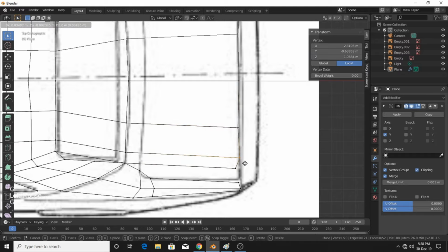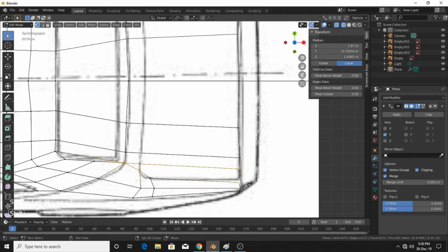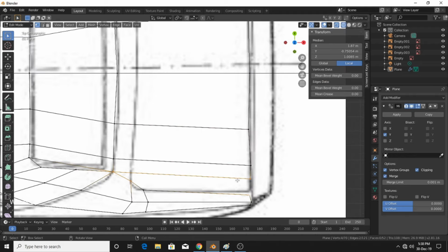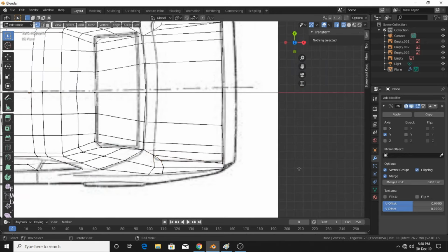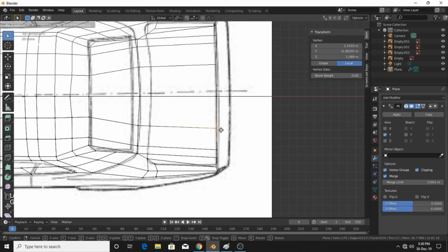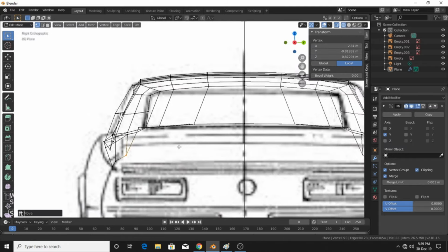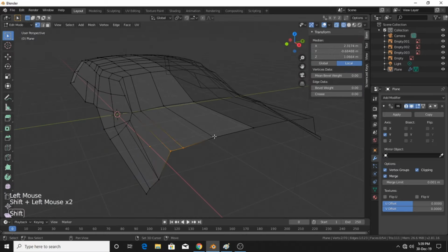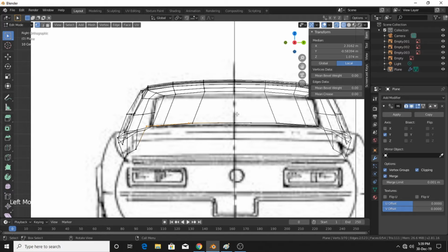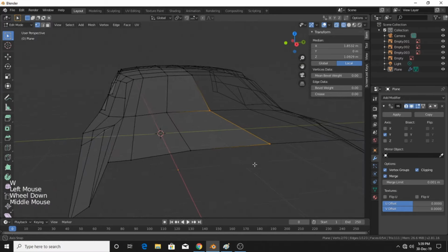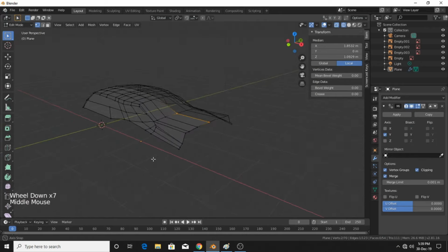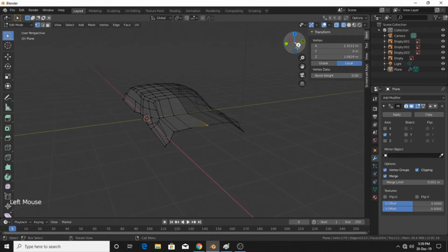Now just select these 3 points and extrude them, and adjust them again with the reference image, and select these four faces and press F to create a face, and then again the triangular face. I am taking this risk to make a triangular face, which is not a good idea for a Blender mesh, because Blender doesn't work well with triangular faces of mesh. Nope.